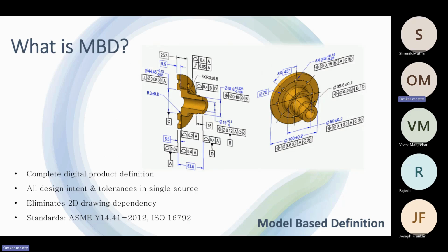So what is exactly MBD, right? A complete digital portfolio for a product definition, with all design intent and tolerance in a single source, eliminating 2D drawing dependency, and it follows the ASME Y14.41-2012 and ISO 16792 standards currently.